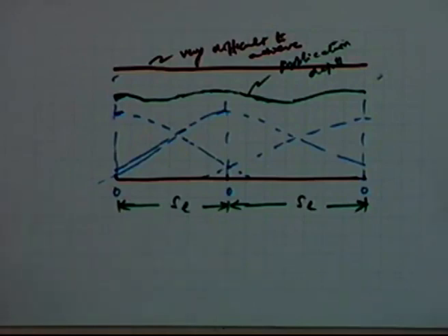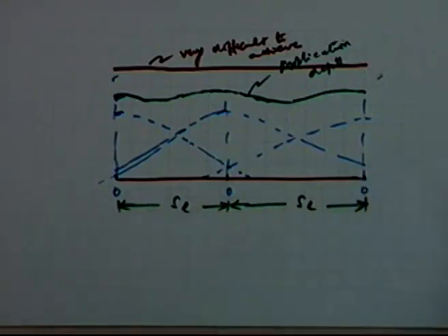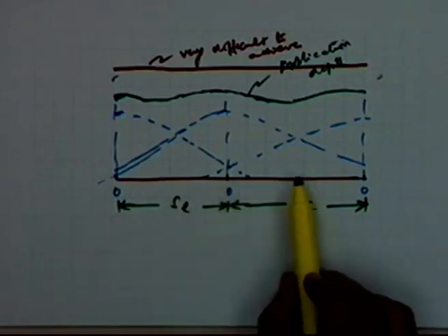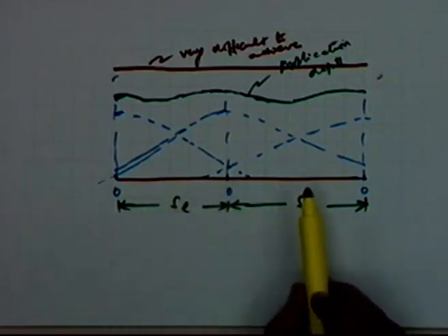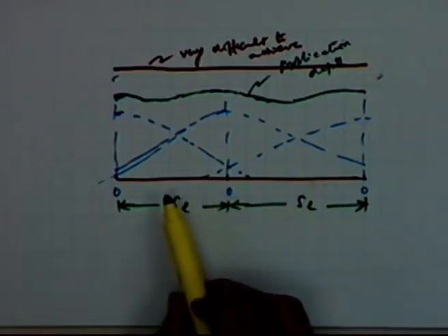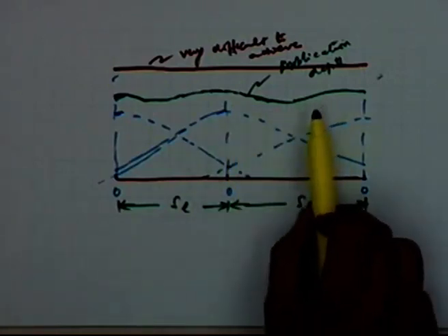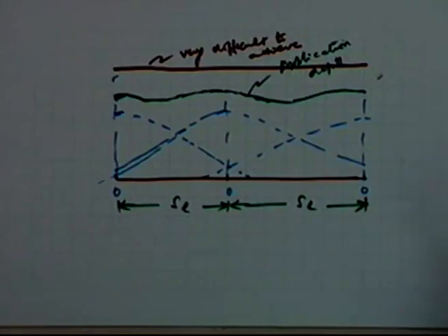And the design aspects in this system pertain to having a combination of these parameters, the two parameters we have just now discussed: the spacing between the laterals and the spacing between the sprinklers on a lateral. These two parameters are very important because they are the ones which will decide the overall distribution pattern. And that in turn will decide the extent of losses. Okay.